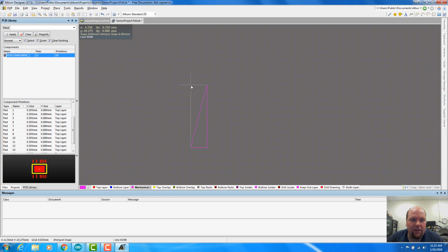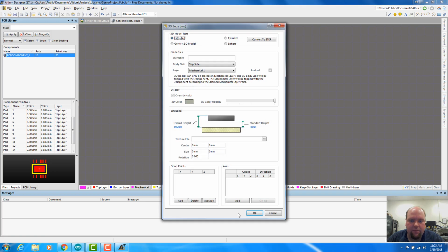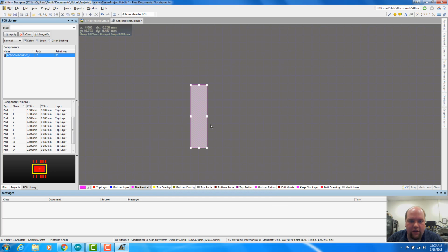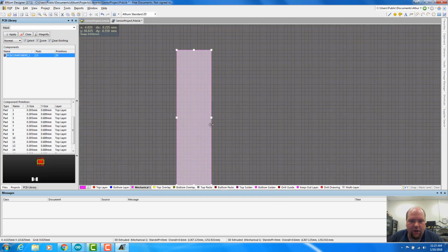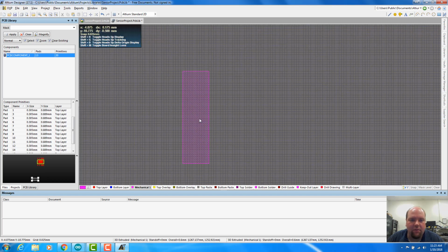Oh, it looks like I made this guy a little bit wrong, so that's alright, we'll fix it. And then hit escape. And then it pops that up, and I'm just going to cancel it. So I actually made this guy a little bit too narrow, so I'm going to click. And I don't want to click on this guy, or it's going to break that. So I'm just going to click off to the side. Make this guy a little bit wider. And we can always check the width. We can click here and move here, and yeah, 0.275 millimeters wide.